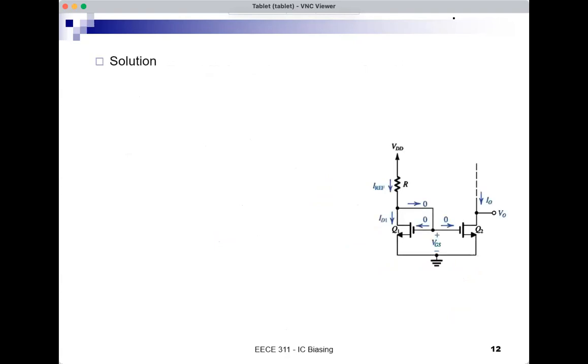That's my circuit, and I'm given that I need to include VA in the DC analysis. So since I'm told to include it, I will show it. I will show the correction factor. And this is the equation now for Q1, MOSFET Q1 in SAT. ID1 is half K prime W over L1, VGS minus VT squared. And then times, because I have to include VA, 1 plus, this is supposed to be VDS1 over VA1.